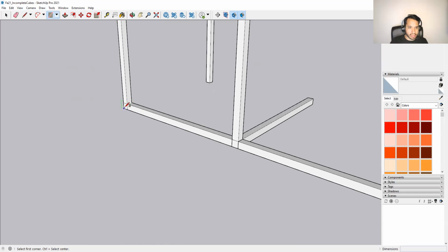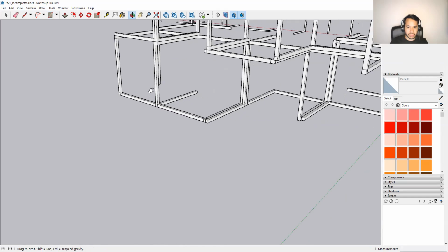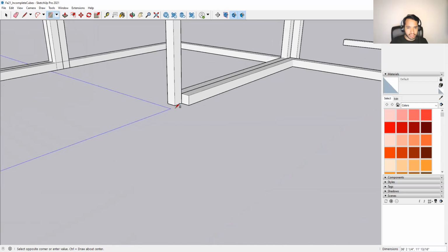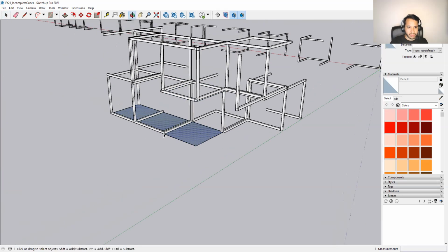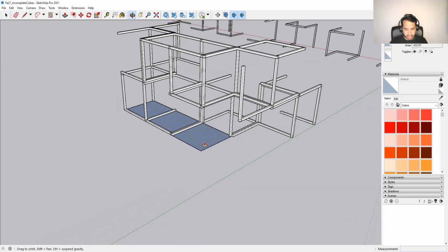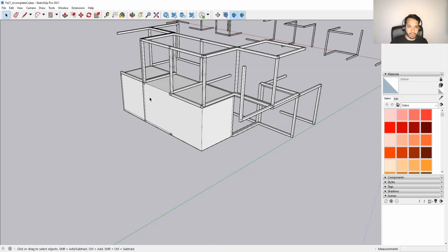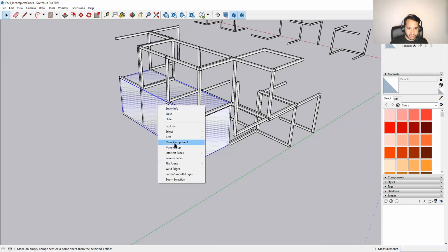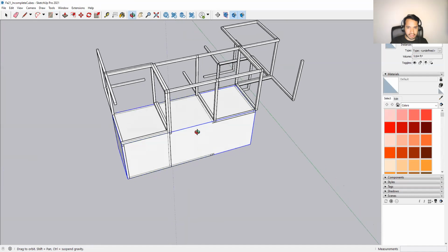Okay. So let's say I'm going to start at the bottom corner here, click, move the cursor, I'm panning over, I'm zooming out, and I'm zooming in to this corner over here. Because this is the edge of this 12 by 12 cube. So now I have this. I'll use the push pull and I'm going to go up 12 feet. Enter. Now remember, once we go up, we always group: 1, 2, 3, right click, make group, right? So here's one of my massings.